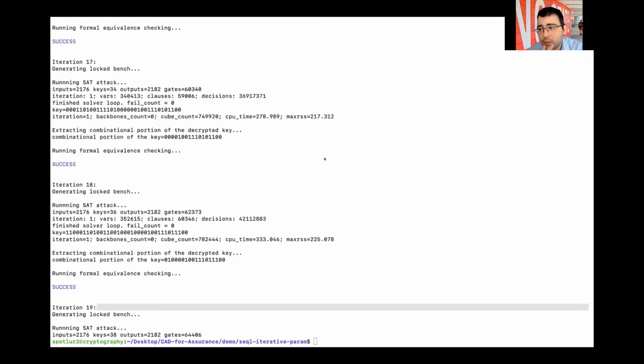So 2 to the power 64 can still be breakable. That's why we typically recommend using 80-bit keys or more, so that it is secure not only against SAT attacks or SMT attacks or other attacks, but also against brute forcing. That's the reason I have locked RISC-V with 100 bits.